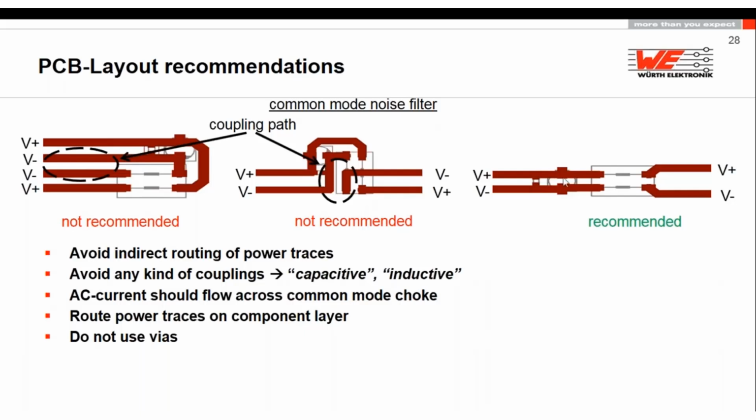With redesign number three, here you can see the capacitors, the common mode choke, and the exit. With this one, he passed the EMC test and he was happy. If I had not seen this first design, I would not believe that such a small PCB, I would say wrong PCB routing, could make such a crucial effect, that you're not talking about 2-3 dB, you're talking about a 15 to 20 dB difference. So please be aware, if you filter something, to not cross or be too close to the cleaned and filtered area.